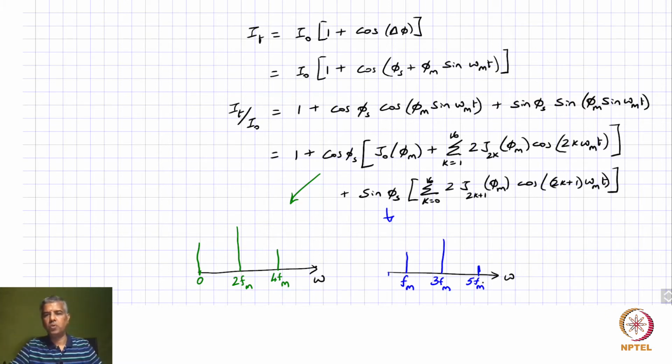So you have both the odd and even Bessel components, which are carrying the phase information that you want to pick up, right. So that's carrying the information about phi s. So essentially you have converted the change in whatever. So if there is a rotation rate, that is showing up in the phase difference, which corresponds to phi s, and that you have now encoded into the Bessel components.